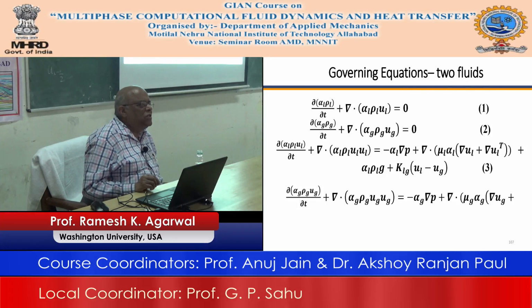In all these cases, the surface tension will be a major parameter. So, surface tension being a major parameter, you will find that the non-dimensional numbers, like of course Reynolds number is always present, the Weber number, and Weber number is a ratio of... that is correct. So, Weber number is going to be important, it is the inertia force divided by surface tension,